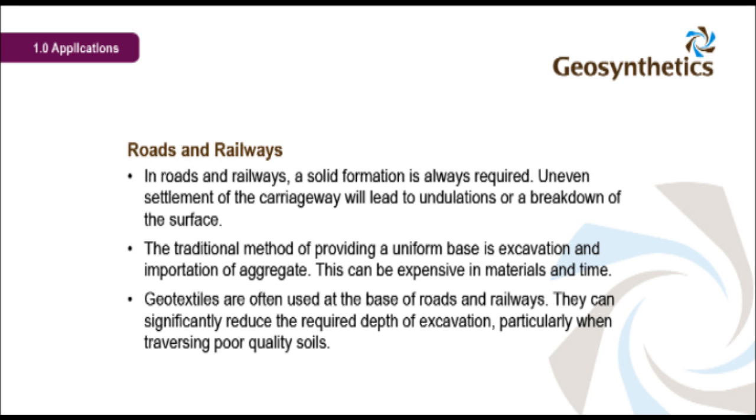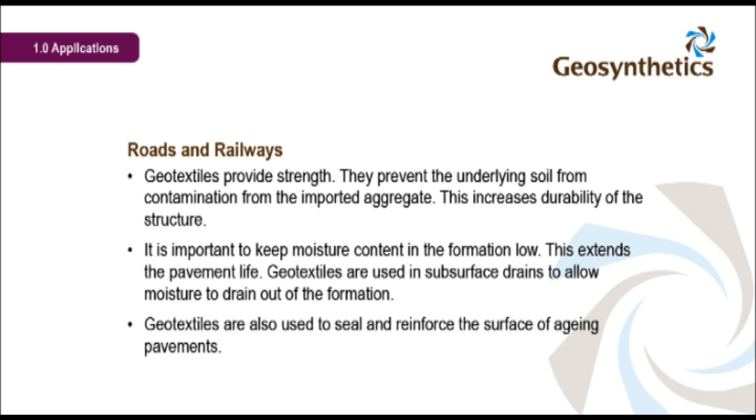Geotextiles are often used at the base of roads and railways. They can significantly reduce the required depth of excavation, particularly when traversing poor quality soils. Geotextiles provide strength. They prevent the underlying soil from contamination from the imported aggregate. This increases durability of the structure.